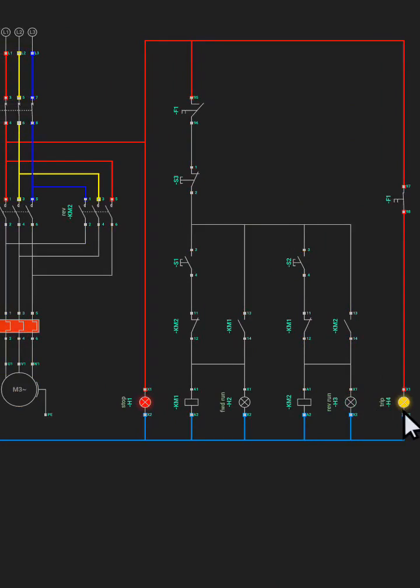What could cause this? Maybe the rotor encountered a kind of jam, maybe the conveyor or the belt is stuck, or what is attached to the rotor is stuck, so the motor is trying to apply pressure and draw current in order to move it.